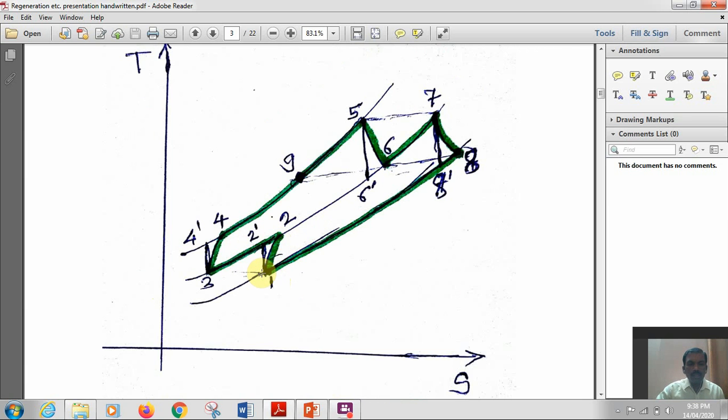In layman's language, this is the lesser temperature difference divided by the higher temperature difference, where the denominator is higher. It is isentropic work divided by actual work. So the efficiency of the compressor is equal to (T2 dash minus T1) upon (T2 minus T1).